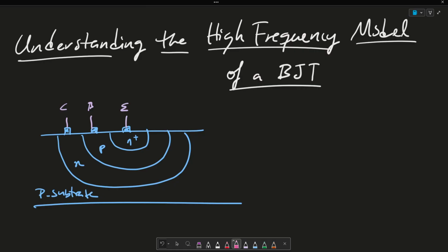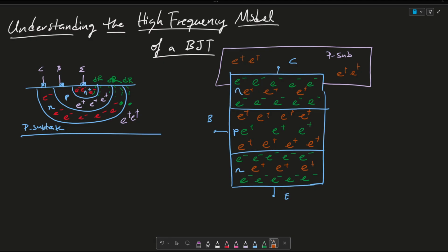All right. So again, remember, N means that it's doped with electrons or negative charges. All right. P means that it's doped with positive charges, or holes. Let me change colors. And again, here again, we have N minus. But essentially what happens is that between the NP channel, we create what is called a depletion region. Okay. And a depletion region here. And another depletion region here.